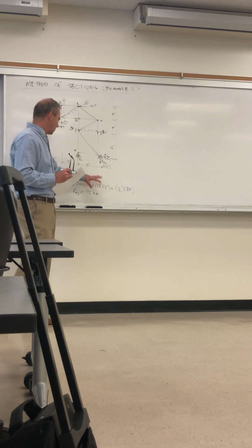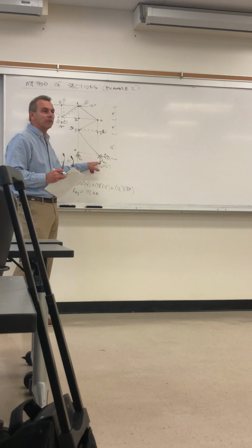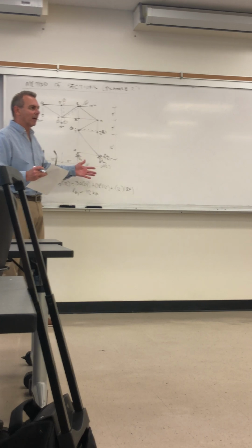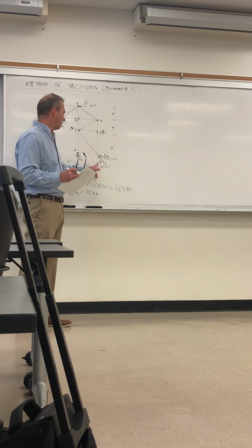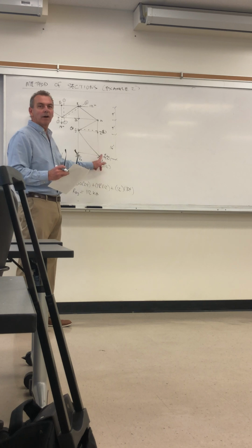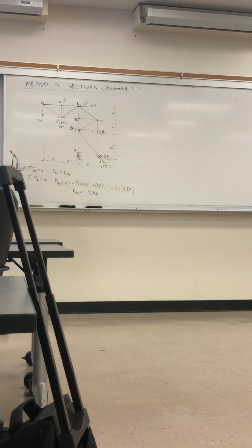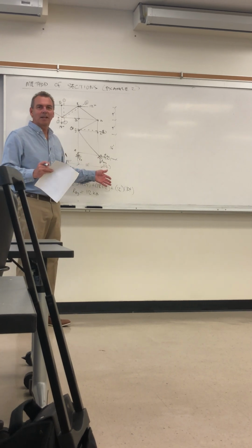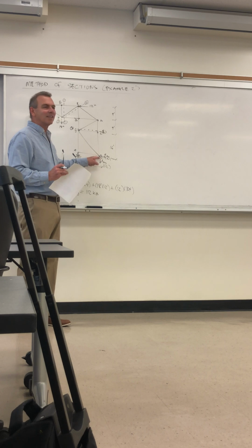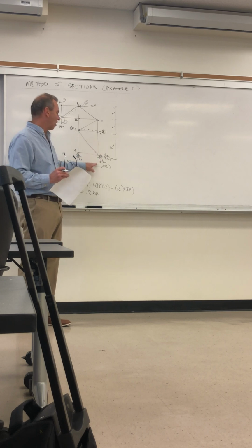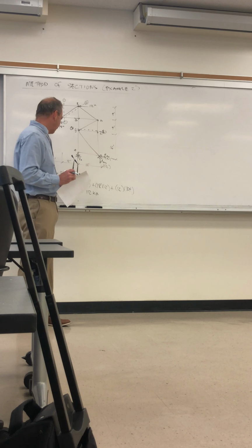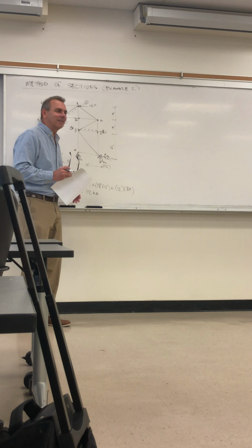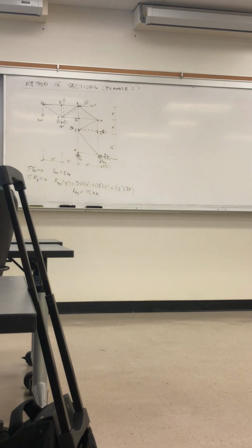If I did this and I came out with a negative, it just means it would be opposite to the way I drew it. I wouldn't redraw it, because then the prior equation is no longer correct, right? But I would add another arrow if it came out to be negative, and then draw it the other way with the value next to it. You get into a lot of trouble if, let's say we did get a negative here, and then you go and erase this, and then change the sign, draw the arrow the other way, and it still says R sub DY, then this equation is no longer valid, right? So it becomes messy. So you have to be very careful.